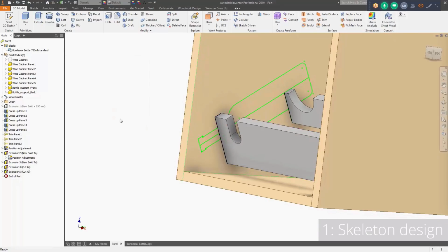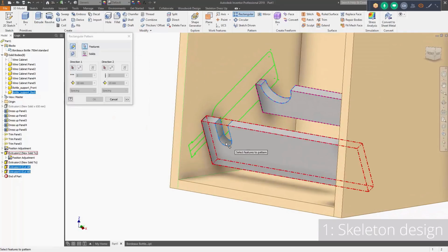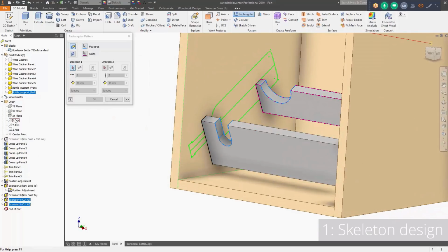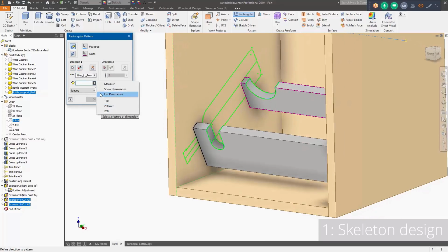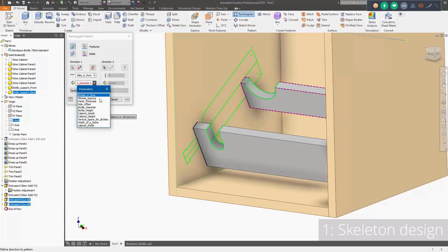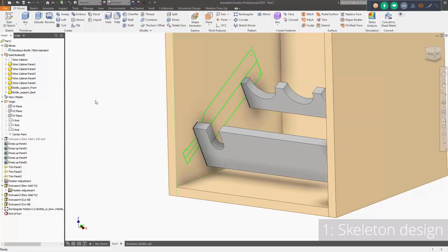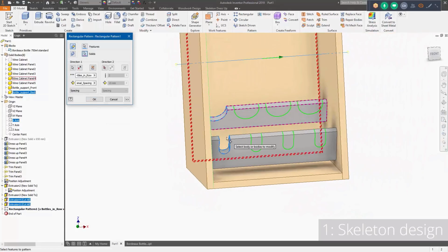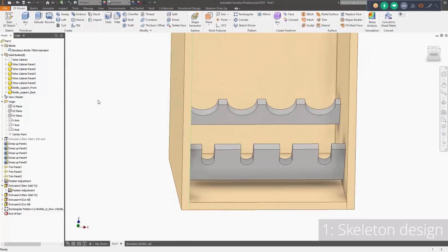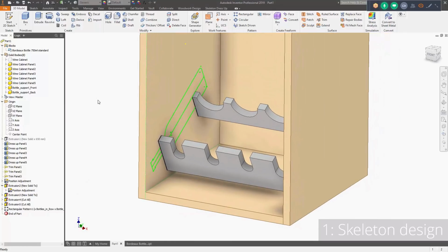And now we want to make a cutout in this solid body. Okay, now we can make a pattern along one of the axes, and those patterns should be done sequentially, because we cannot do pattern in 2 different solid bodies. Yeah, that's the limitation of Inventor in this version. So let's do another pattern, give the part at the front, like that.